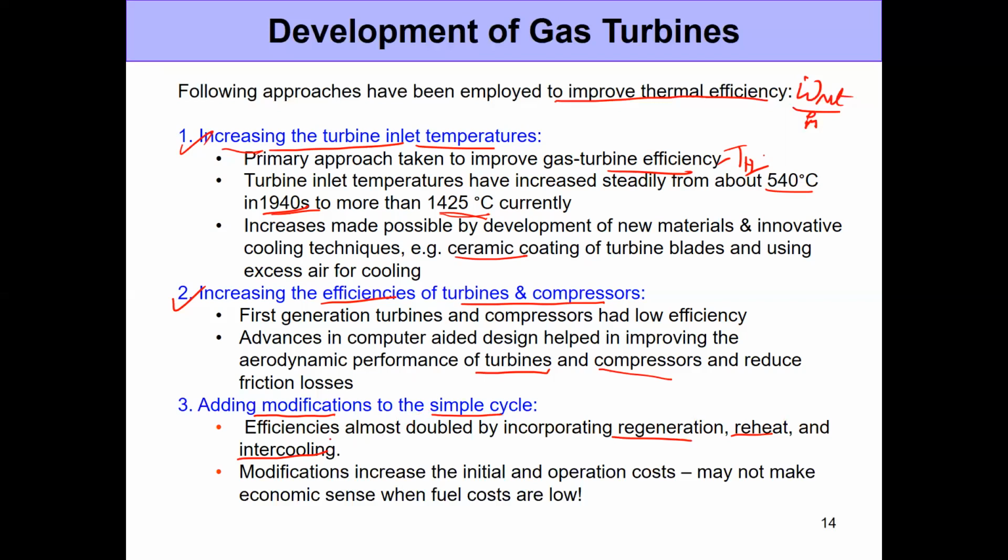Although these modifications tend to not exist in all turbine power plant designs, depending on the turbine inlet temperatures, they still continue to exist in older designs where the turbine inlet temperatures were slightly lower. And the reason why these modifications have worked sometimes, or have not been implemented in others, has simply to do with the economic cost of it.